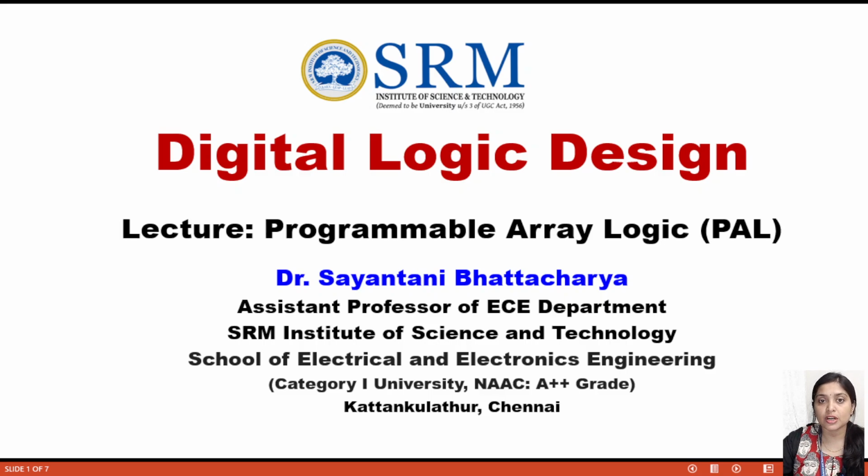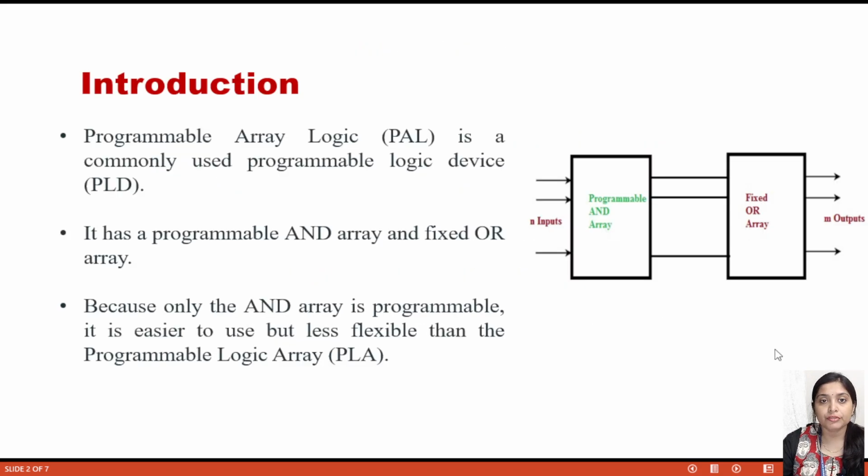Today I am going to start a new topic of digital logic design: programmable array logic. So, what is programmable array logic? It is a commonly used programmable logic device, known as PLD, and it has a programmable AND array and a fixed OR array. This is the diagram. Here the AND array is programmable and the OR part is fixed.